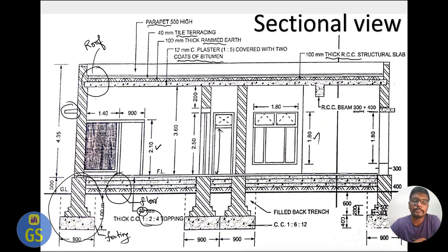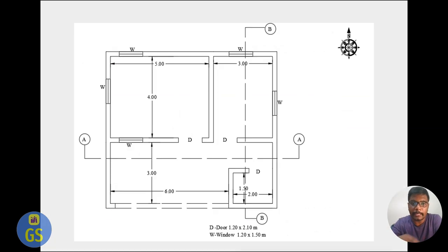Basically the step footings are provided in residential buildings when your columns have less loads. When the columns have less load, we generally prepare a step footing. And also you need to take care of the soil bearing capacity as well. So here the step footings are shown. I will show you in detail how these calculations are to be done and how these are calculated in drawings. So let's go ahead.